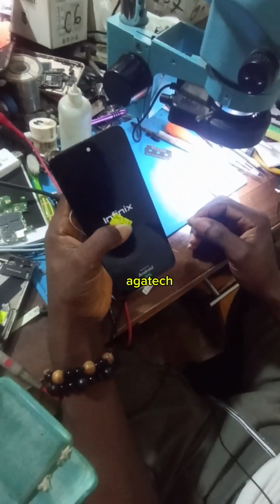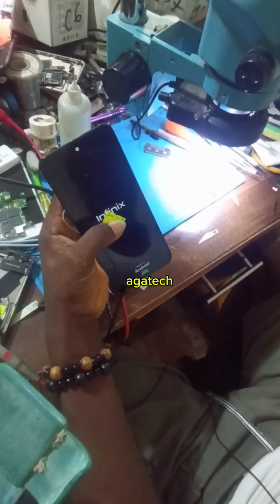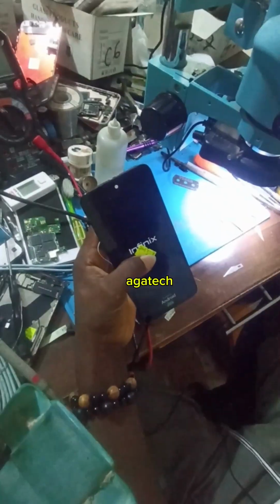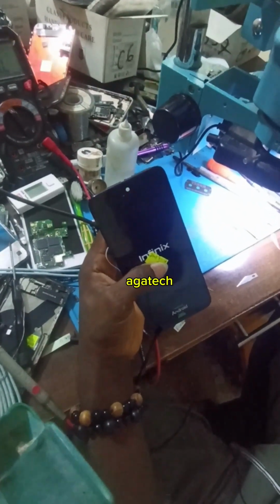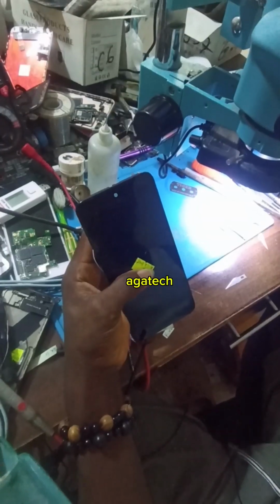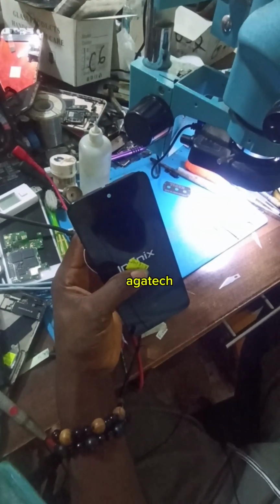So the phone is working now. The FPC connector on the board was bad, the FPC connector on the screen was bad, and the fuse in the backlight circuit was bad. So fixing the three of them fixed the phone, and the phone is ready to serve the customer again.